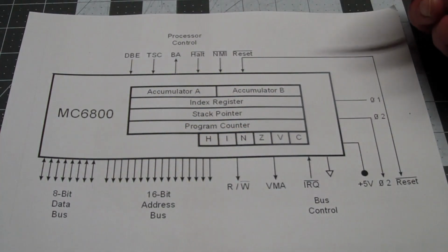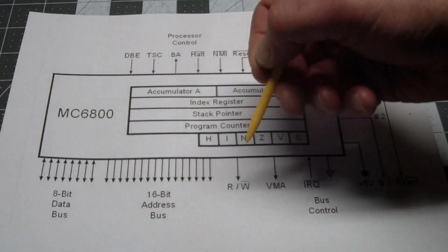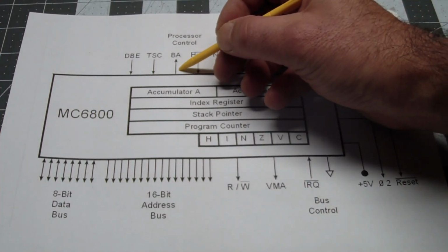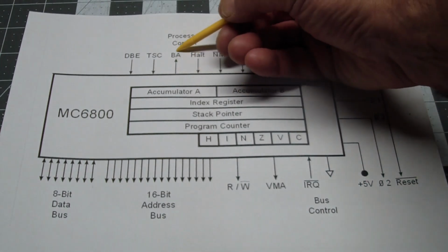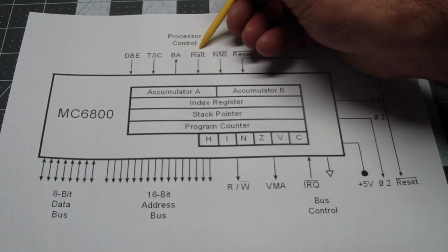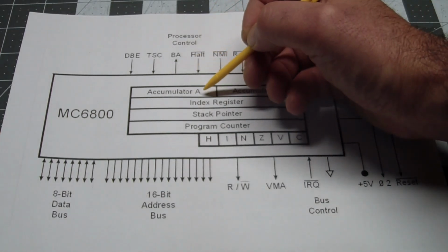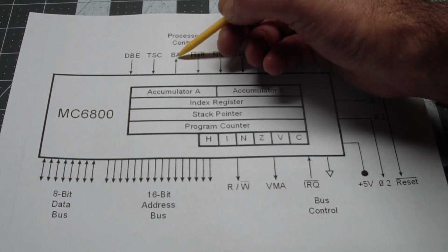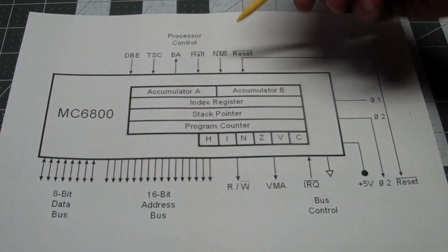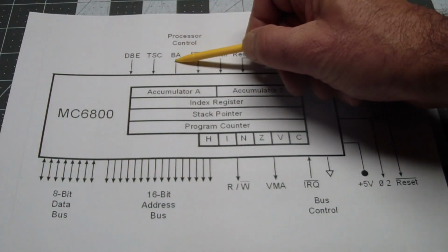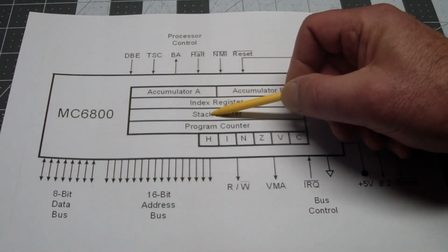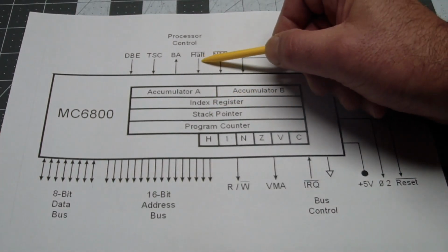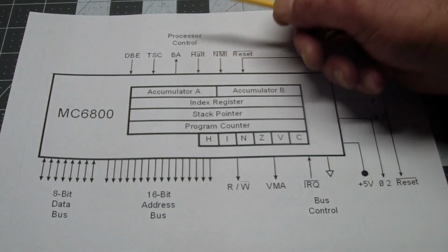And when that procedure is completed, it asserts the BA signal, making it go high, and telling whomever did a halt request that the halt request has been processed, and the rest of the bus is now ready to be manipulated by something external, because this guy's going to stay asleep until the halt signal goes back high again.